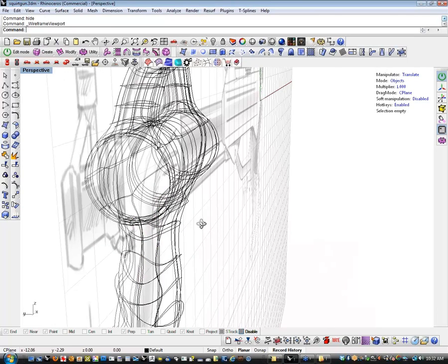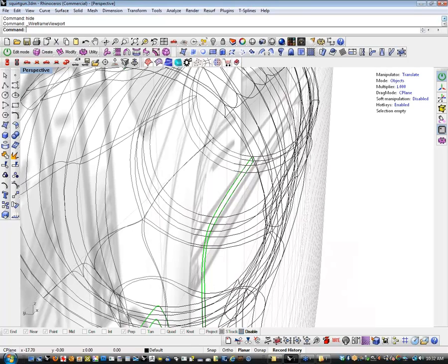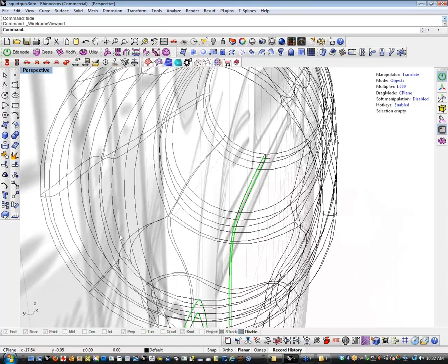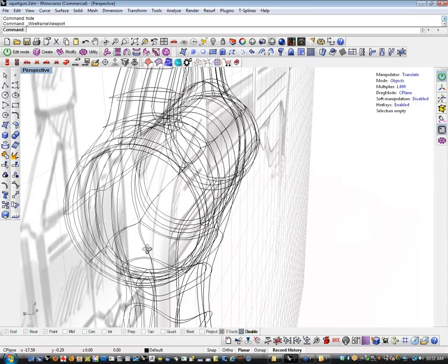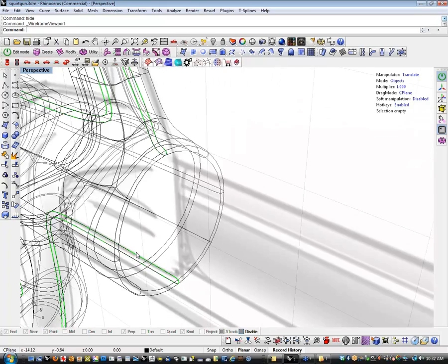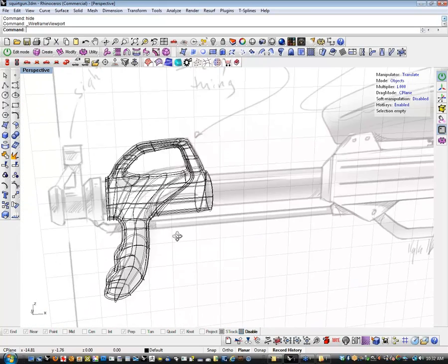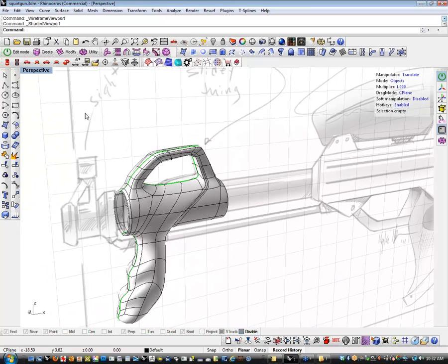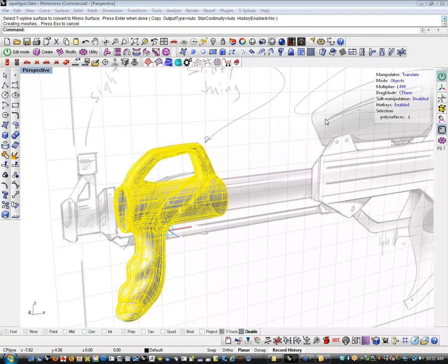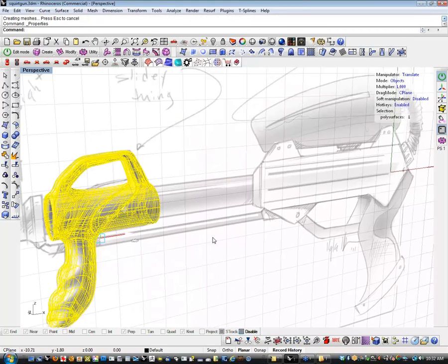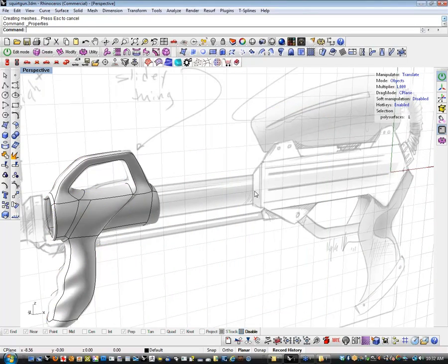First of all, you'll notice that it does have an internal and external surface, and I did not take the time to specify a wall thickness, but if I had, this would be the specified wall thickness. Now, if I convert this to NURBS, which is simply a single button click here, this is now a NURBS polysurface, and if we look up here in the window, you can see it's a NURBS polysurface. Let me get rid of some of the ISO curves because it's got a lot of ISO curves in it.